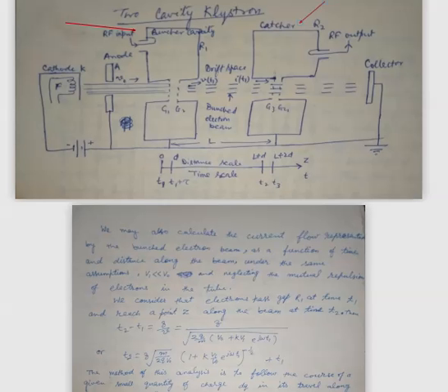and due to the application of the small RF input signal between these grids, the steady electron beam which passes through the cavity grids G1, G2, due to the alternating potential between G1 and G2, there will be a change in the velocity of the electrons, and the electron velocity after coming out from the buncher cavity grids will be a function of time, and therefore we can say that the velocity modulation takes place.